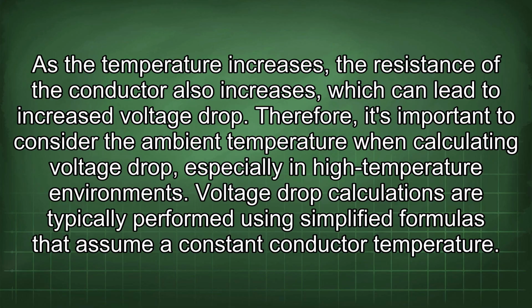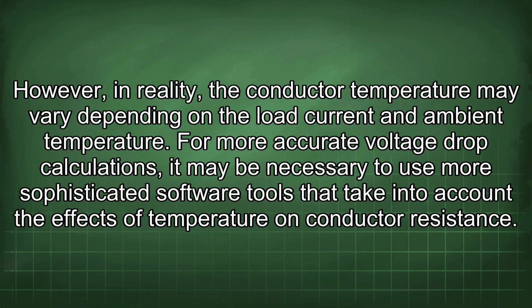Voltage drop calculations are typically performed using simplified formulas that assume a constant conductor temperature. However, in reality, the conductor temperature may vary depending on the load current and ambient temperature. For more accurate voltage drop calculations, it may be necessary to use more sophisticated software tools that take into account the effects of temperature on conductor resistance.